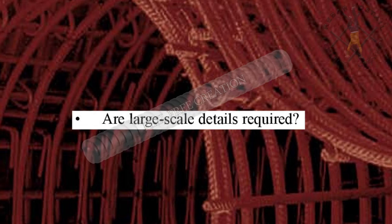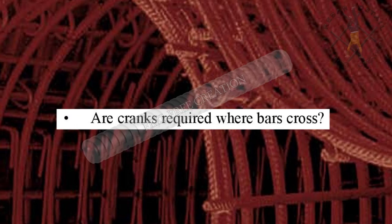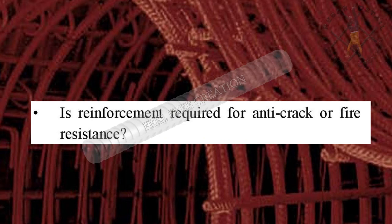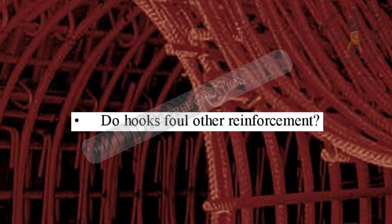Point 21, are large-scale details required? Point 22, are cranks required where bars cross? Point 23, is spacing of reinforcement correct both on plan and section? Point 24, is reinforcement required for anti-crack or fire resistance? Point 25, do hooks foul other reinforcement?